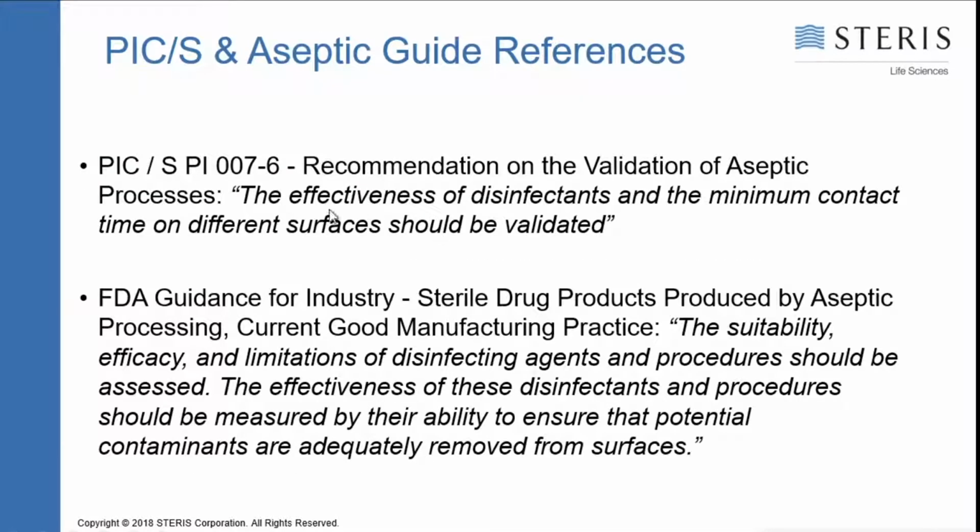And then, of course, a couple of other nice little guidance documents out there would be the PICS document. If you read the latest version of PICS, you'll notice that it says the effectiveness of disinfectants and minimum contact time should be considered on different surfaces when they're validated. And the FDA aseptic guide also talks about the need to validate these products on the surfaces in the clean room to make sure that they are working adequately.